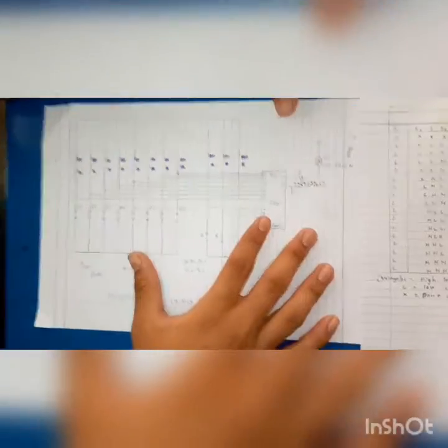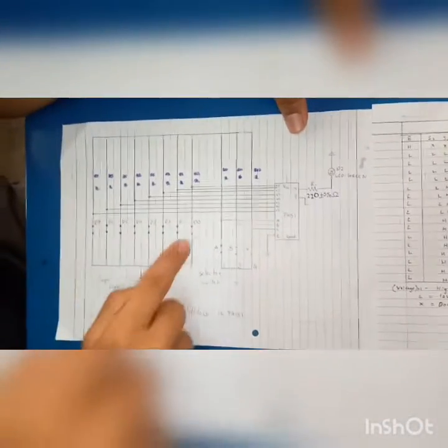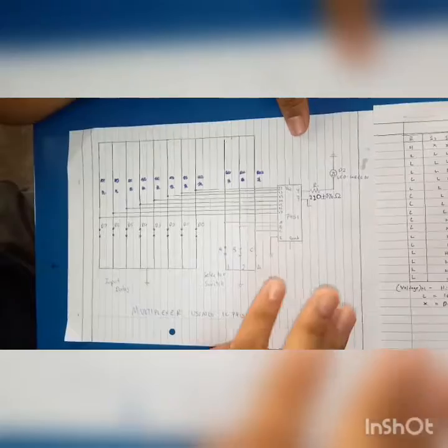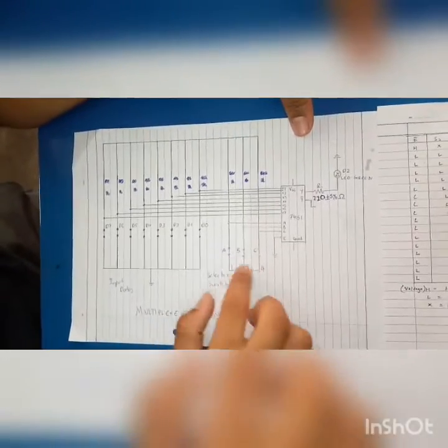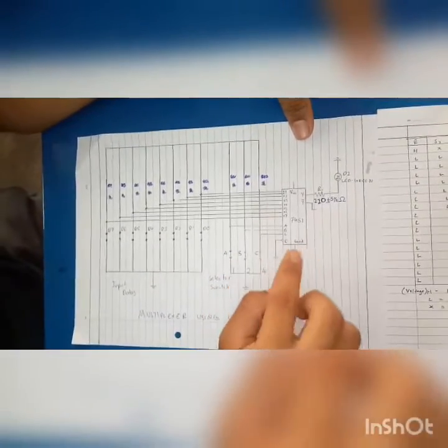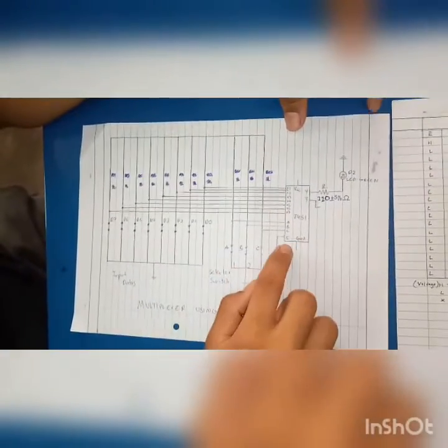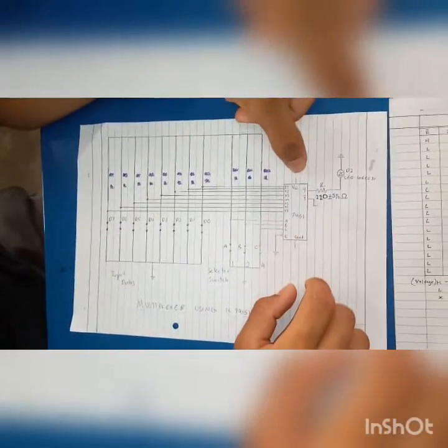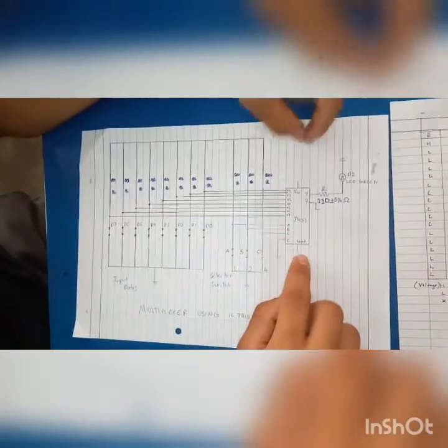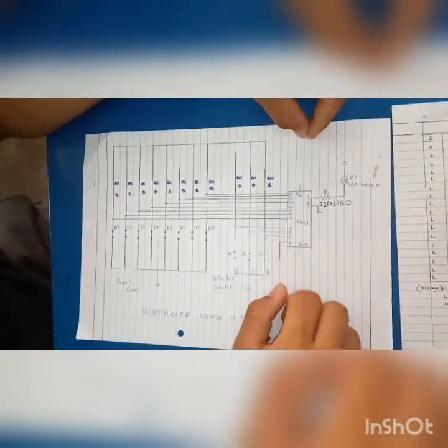So today we'll be explaining our assignment, which is the multiplexer 8 to 1 using IC 74151. This is a diagram of our circuit. We have 8 input data, D0 to D7, and 3 selectors, A, B and C. We connected all of these inputs at the negative side to the ground, also with E. They are connected to the same ground, and we have also the VCC connected to the power source, the positive end, and the ground is at the negative end.